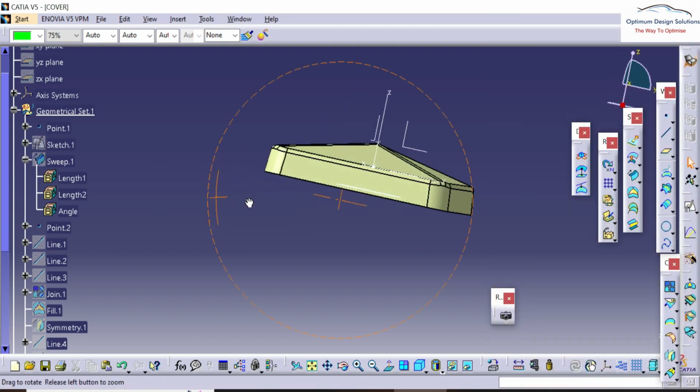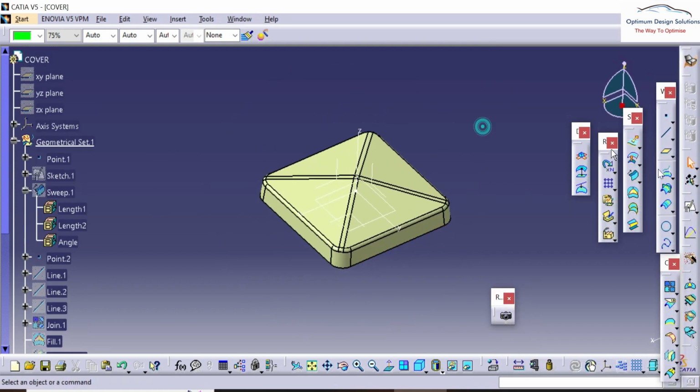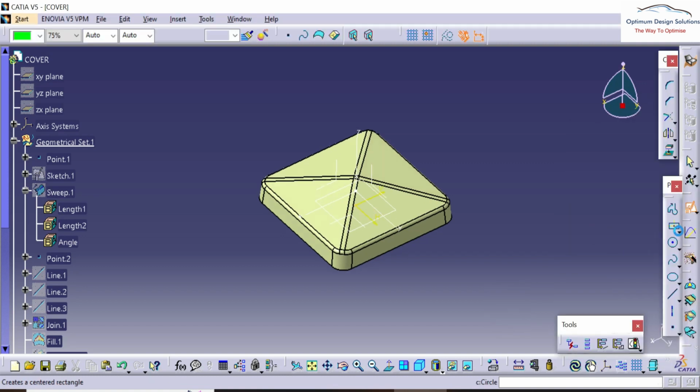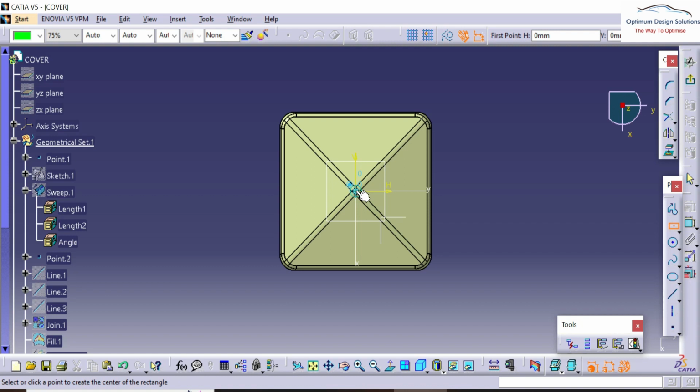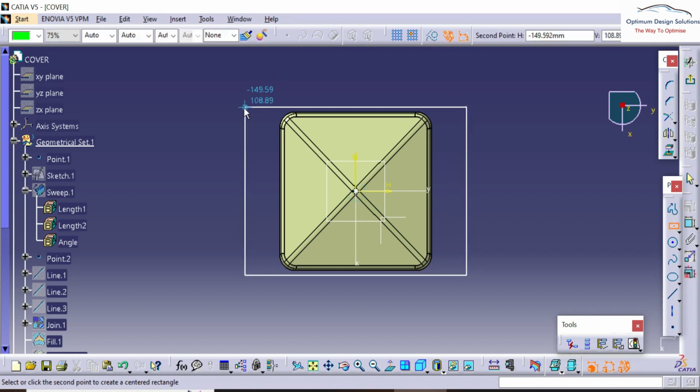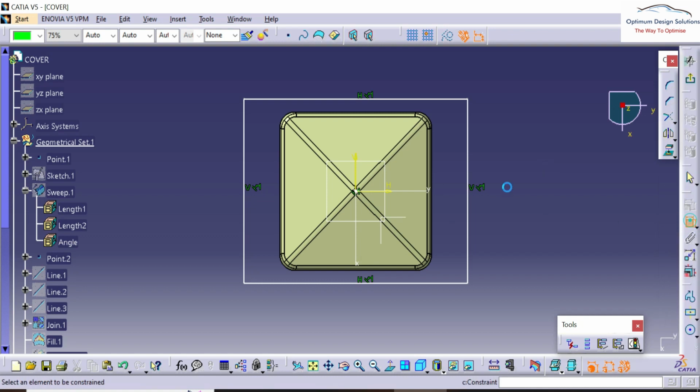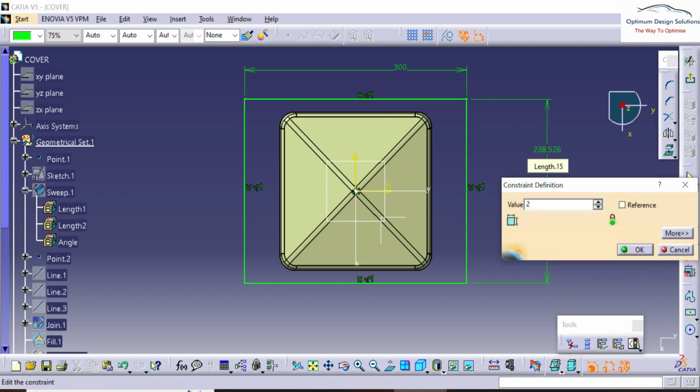I will just increase that bottom side draft area, the length of that draft area, as we have translated our particular plane 25 mm. Same way we create the bottom mounting face, which is the mating face, where we are going to mount our cover on the assembly.